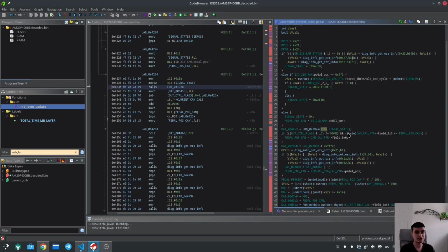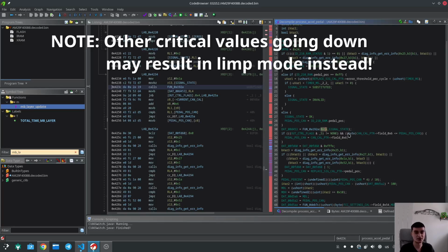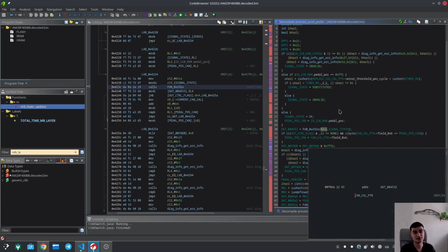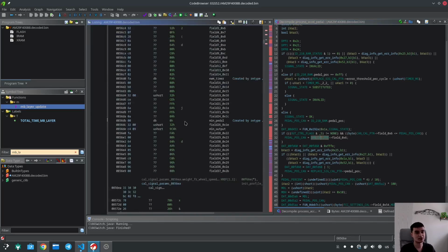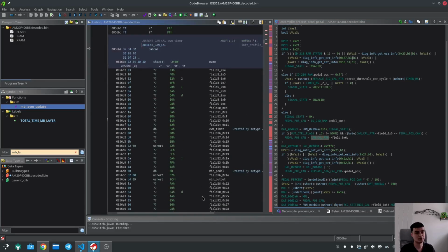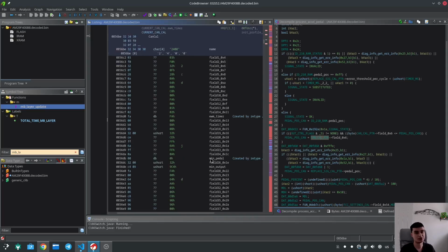This is how the TCU deals with situations whereby, for instance, maybe CAN is dead for a few seconds or so. It just substitutes some values. This comes from the CAN bus, well, I called it the CAN bus calibration, but I don't actually know realistically what it is, and we can have a look at that here. It's just a structure with a bunch of values which are for substitution.